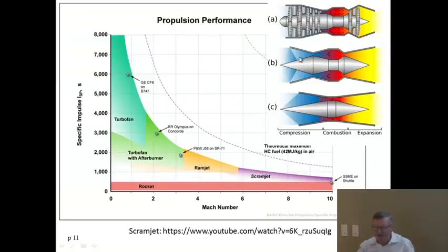So the ramjet is in fact the same as the scramjet. It's basically an afterburner here, and the compressor stage is made simply by narrowing the shape of the duct, which increases the pressure on this side. So here you can transform your incoming velocity into a higher pressure, then you let it go.